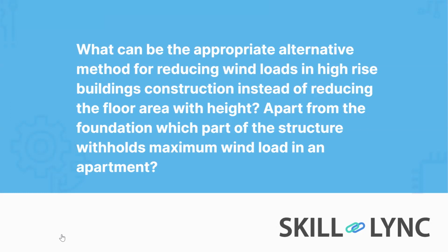So basically, you're allowing the wind at that level to pass through the building, and they use this open floor as sky gardens or some sort of recreational activities or restaurants or whatever. So the architects come up with various ways to use this open space. You can see examples of various buildings with sky gardens at higher levels. So one reason for providing this is to reduce the wind load on the building.